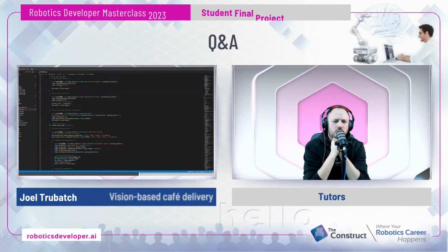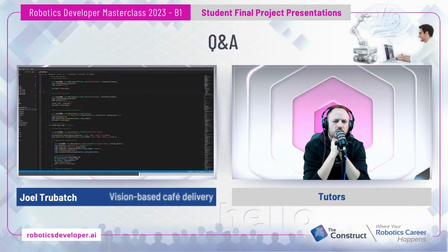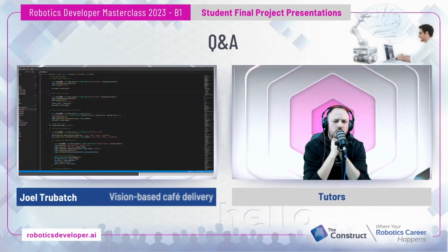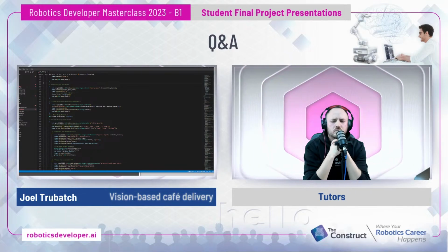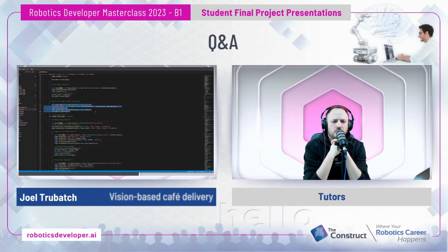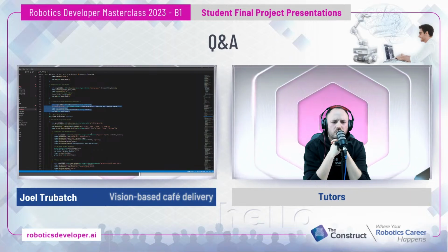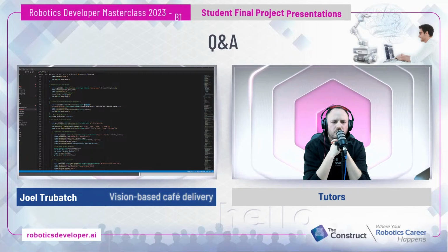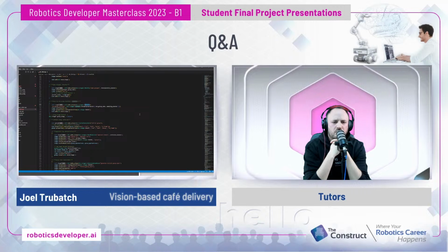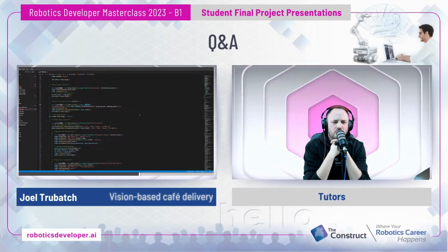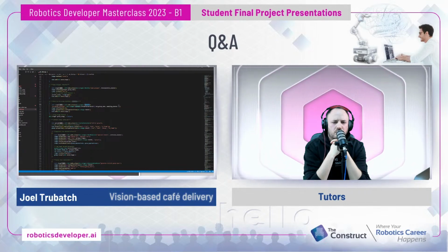And so these pass information forward. Like this, any information generated by this would automatically be passed to the next stage here. This stage goes from that initial arm position to the grasp stage. And so this is a connector stage, as they call it. This doesn't technically pass any information. It just tries to solve between two positions.